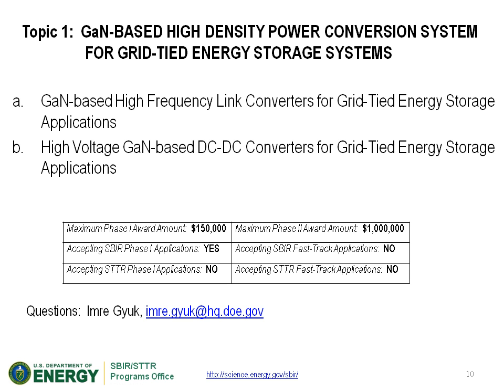Now, topic B is primarily focused on a gallium nitride-based DC to DC converter. That's the main focus. It's not a high-frequency link like topic A, but this is a typical DC to DC converter, but using gallium nitride switches for this conversion. And the requirement for that is the boost voltage of greater than 600 volts DC, greater than 98% efficiency, greater than 20 kilohertz switching frequency, and 2 times increase in power density. Again, we must show significant improvement over silicon-based systems.